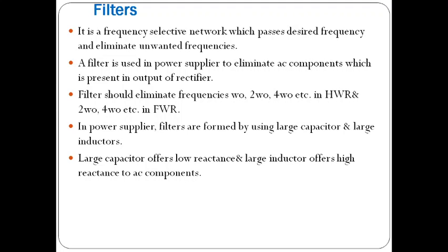This large capacitance offers low reactance and a large inductor offers high reactance to the AC components. By using the capacitor and inductor as filters, we can eliminate the unwanted AC components from the output of rectifier circuits.